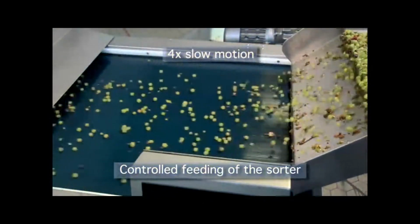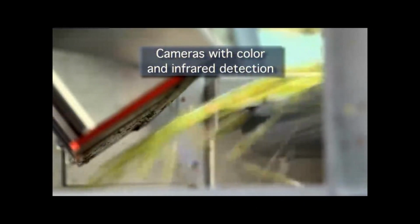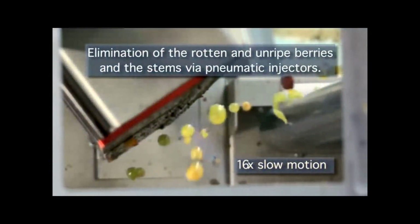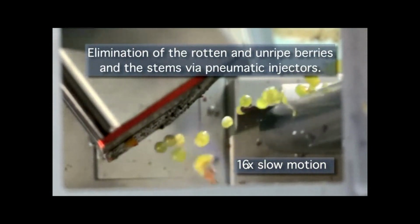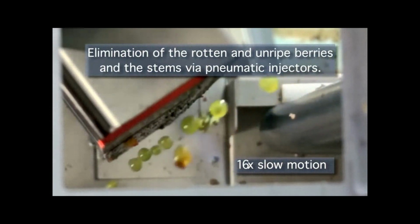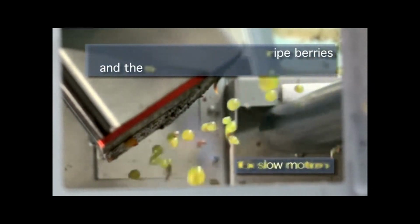So here you also have what they call the camera. So you remember the photometric cell that I've shown you, which takes the pictures of these materials as they pass. So these are cameras with color and infrared detection. So as the material passes, compressed air removes those materials that are not desirable. It shoots them at a very high speed. So this is a process that happens very quickly at a very high speed, right? But this is very fast. So any material that is not required is thrown out of the process.